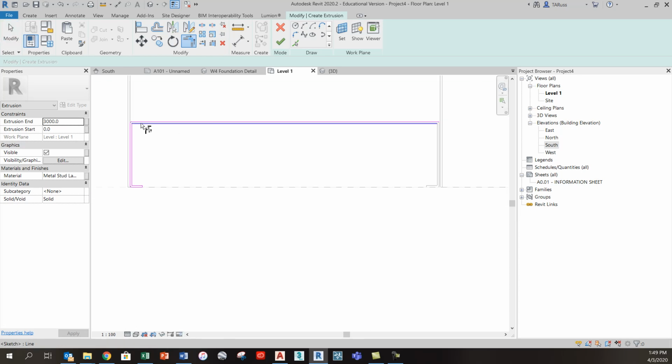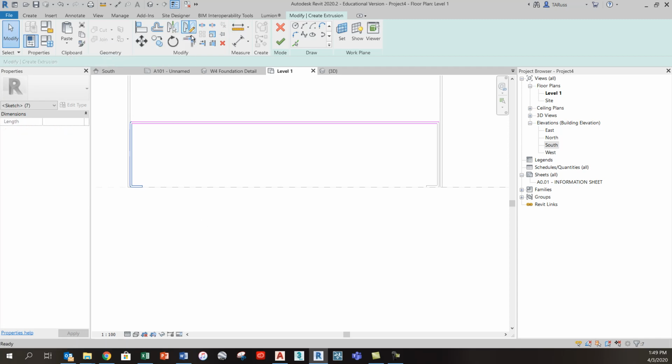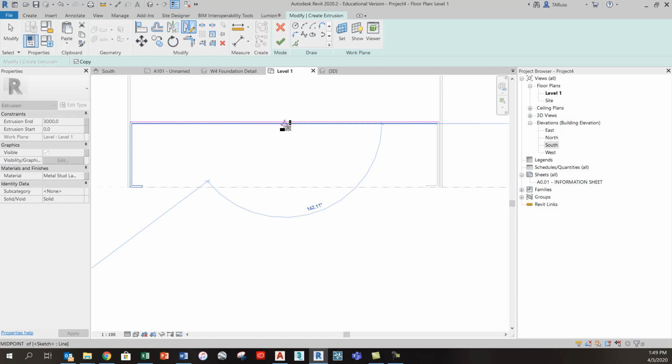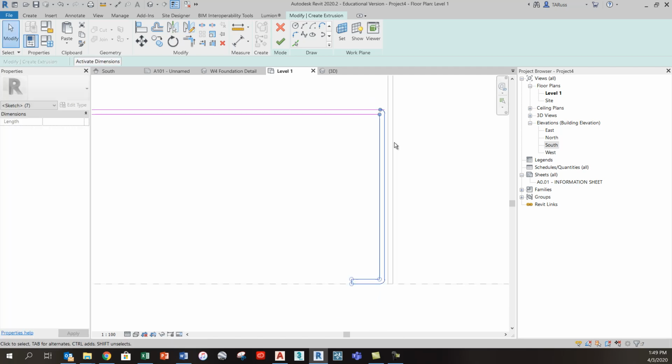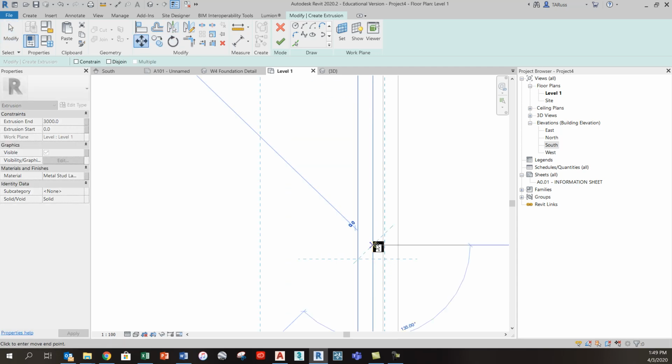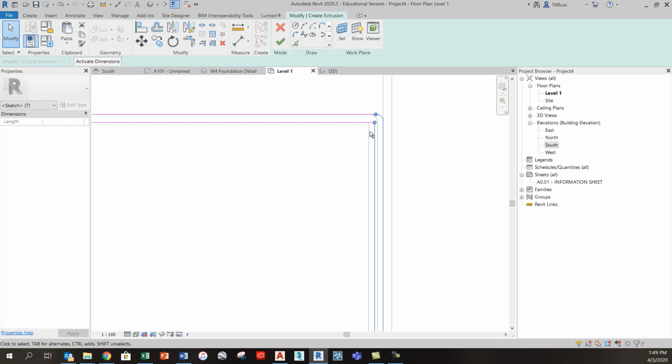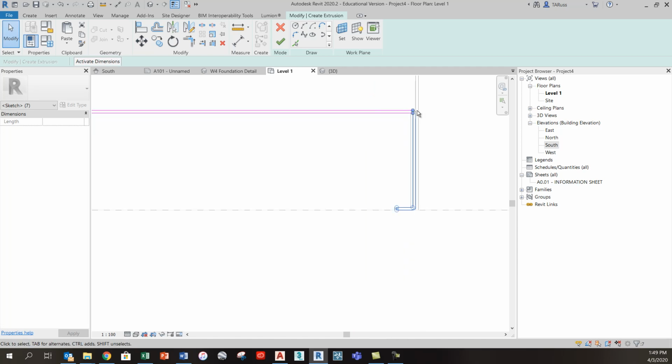And I can start that process by clicking on what I've already got using the mirror draw axis tool. I'll snap to the midpoint. You'll see that it now sits in exactly the same spot over on the right, but I'm going to use my move tool and just extend that out so that I get something that's a little bit more accurate for that 152.4.